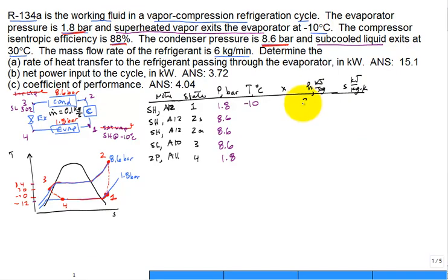So we have 242.06 and 0.9362. All right. Well, the assumption, we do it in 2 steps, so we just bring this down for state 2s, 0.9362. And now the question is knowing this pressure and entropy, can I get the enthalpy, H? Well, it's a little bit of work. We have to do some interpolation. And I don't know if I have that interpolation.